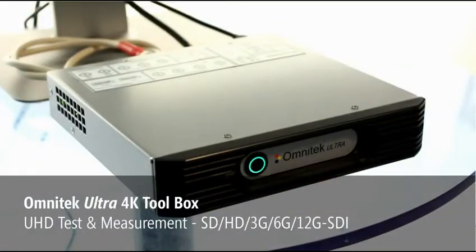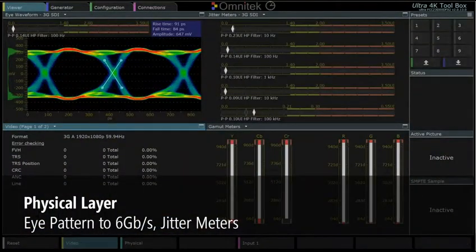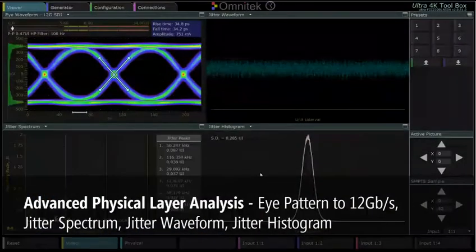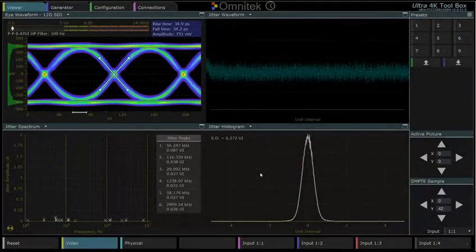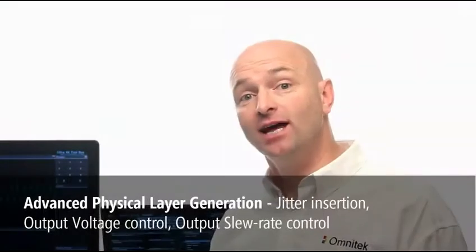So the advanced physical layer builds upon the standard physical layer in the 4K toolbox, which gives you eye pattern and jitter meters up to 6 GHz. The advanced physical layer extends this eye pattern to 12 GHz and also adds a jitter spectrum, jitter waveform and jitter histogram on the analysis side. On the generation side, it enables you to insert jitter onto your signal of a controlled amplitude and frequency, and it also enables you to adjust the output voltage and output slew rate.